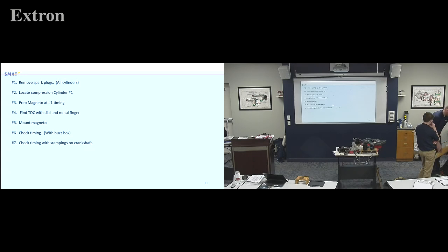And on this one, if I bring it around, the Continentals will show similar. They'll show you top center, but before top center they'll also have a range of like 26 to 32. That's gonna be the range of where a mag would typically go in. And we'll have that on slideshows later. I think they're often 2-degree increments per dash. You can confuse yourself pretty easy, but, yep. All right, I'm gonna go walk out towards that one.